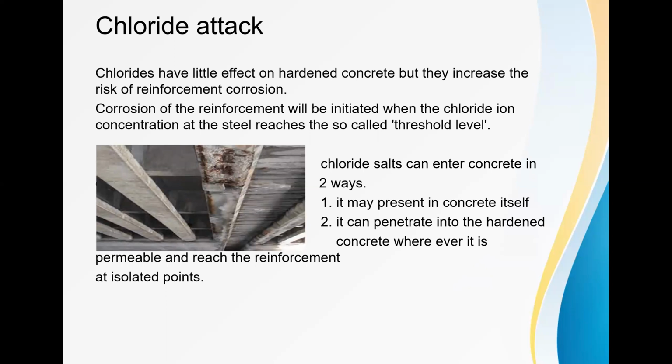These chloride salts can enter the concrete in two different ways. They may be present in the concrete itself, or they can penetrate into the hardened concrete wherever it is permeable and reach the reinforcement at isolated points.